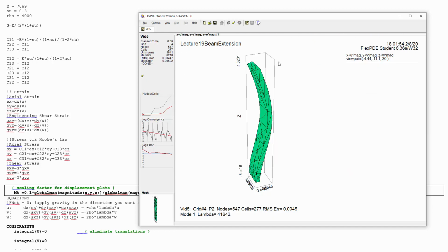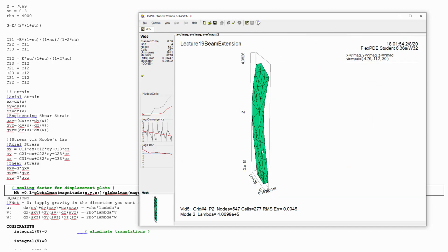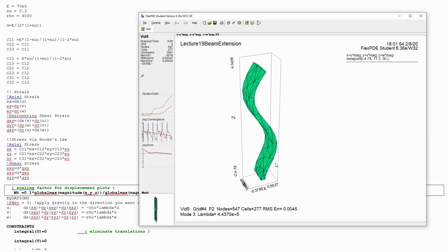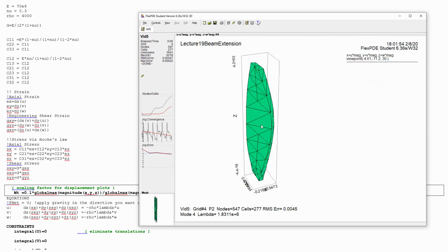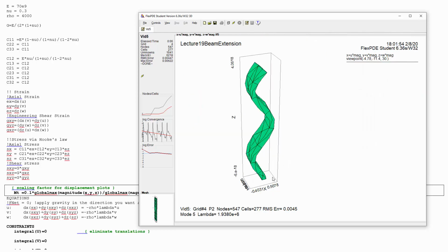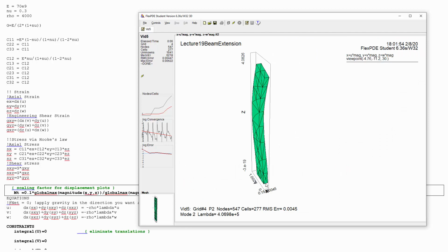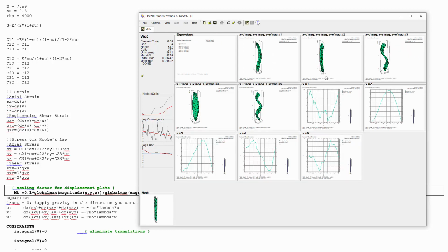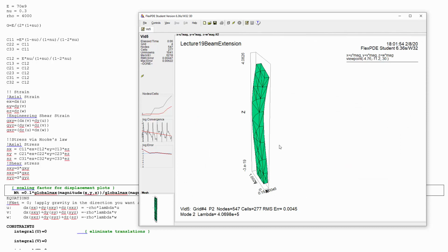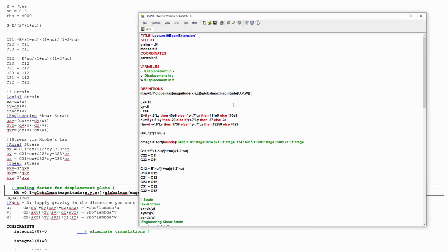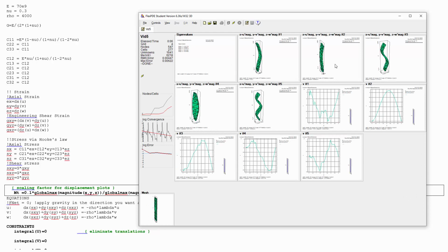Okay, so now our resonant modes are always going to be scaled to something that we can view and see what's going on. And it seems as though we've got some twisting modes, we've got these snaking modes along the length direction, another one there. The one that we were looking for was this side-to-side bending mode, but not this one here. The one that we had in the flex code, which originally had an omega of about 3455, it was a little bit higher order than this.